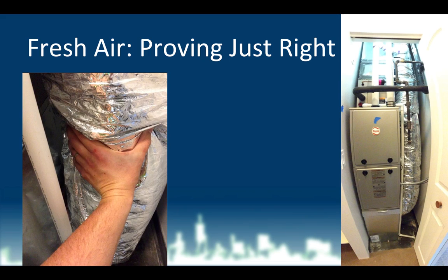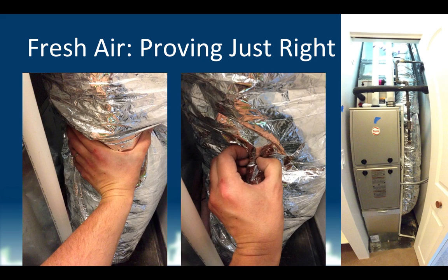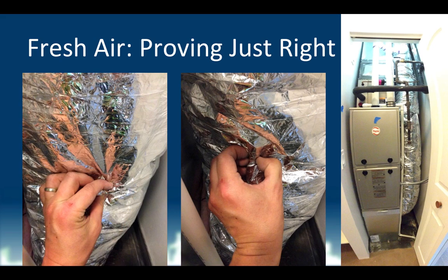I'm an idiot. So once I've molested this thing and I find this handle, now I can manipulate the handle. That's straight up and down. That means that the damper is wide open. This is side to side. That means that the damper is totally closed. I'm going to have to find the happy medium in there by measuring it.